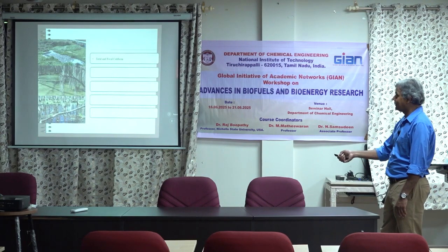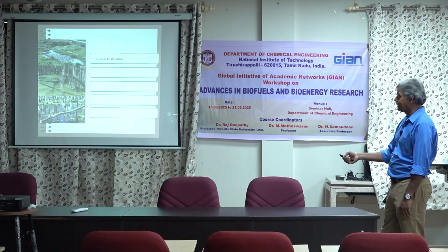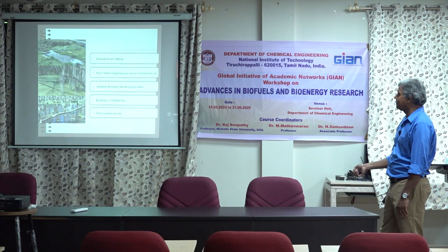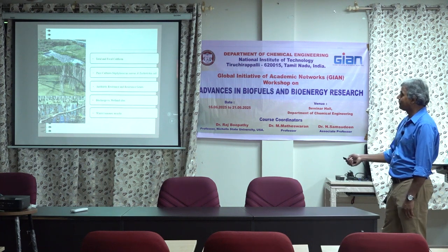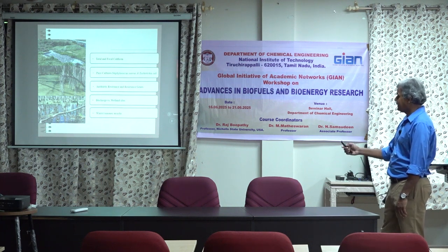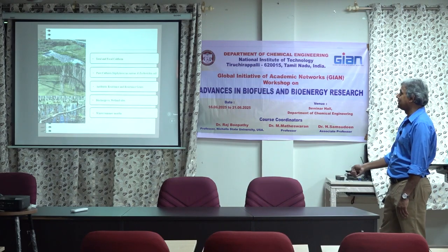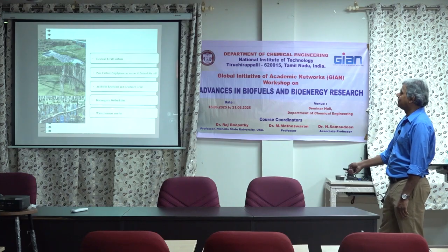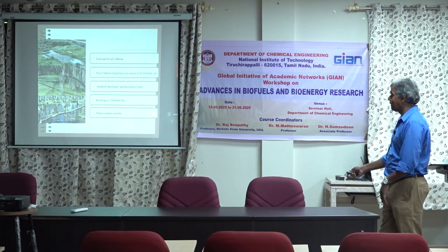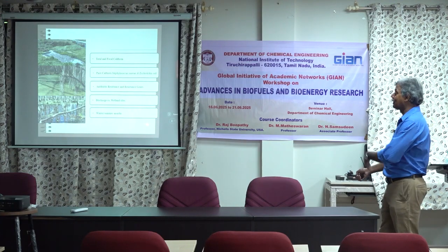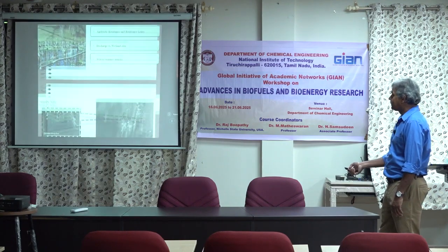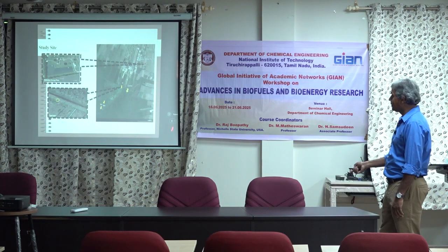That's our wetland. You can see algae all over the surface of the water. We looked at indicator organisms like fecal coliform and total coliform bacteria. We looked at two species, one gram-positive and one gram-negative, that are resistant to antibiotics, to see whether they are reduced in this system. And we looked at the water going in and the water coming out of the wetland. We monitored in winter and summer months. Okay.